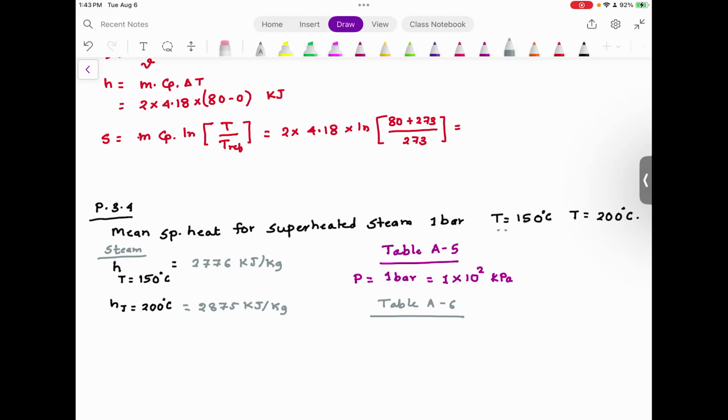Sorry, you don't have the complete Mollier diagram, but when I was a student, I had a Mollier diagram this huge size. The same information we got from the charts and tables, you can also get from the Mollier diagram. But the beauty of the Mollier diagram, compared to the table, is you get all the information in one shot. Once you locate the point on that diagram, it gives you specific volume, enthalpy, entropy, and all the information that you need. Everyone understood?